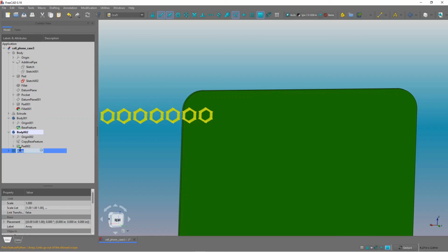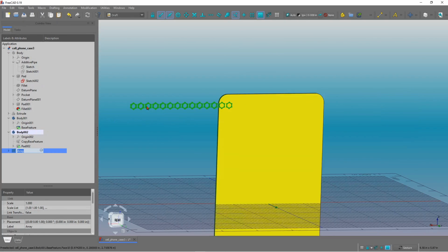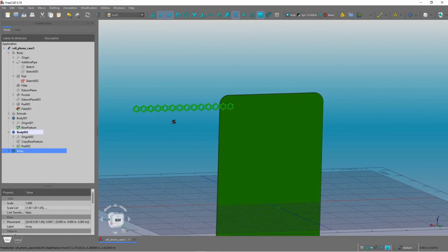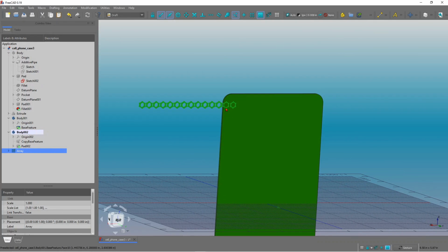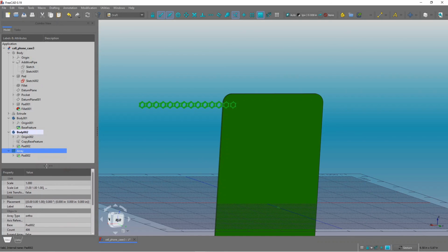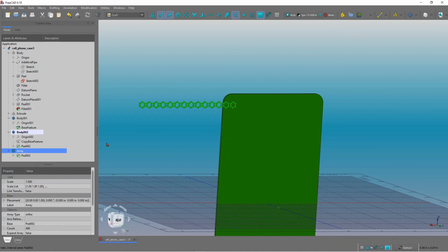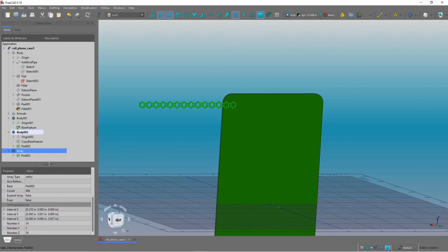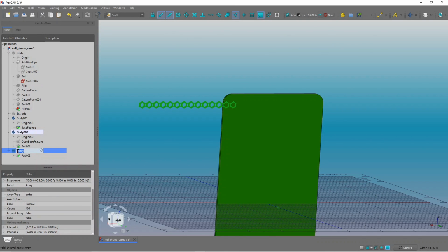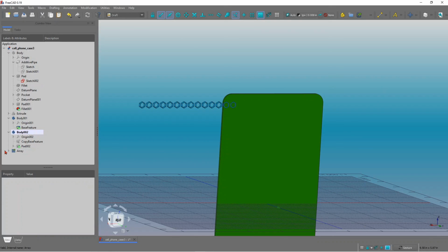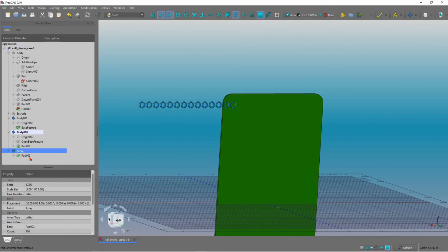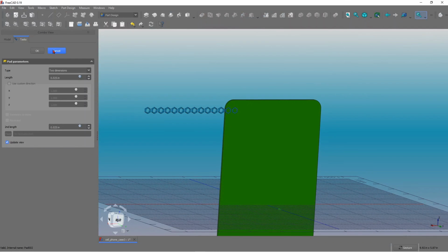Okay, so it created an array only in X direction, 14. Now I had a fat finger issue there. I pressed it too fast and I got out of the array. So now, since I'm already out, if I try to go back, it probably won't allow me to go back for some reason. So it doesn't allow me to go back, so that's fine.